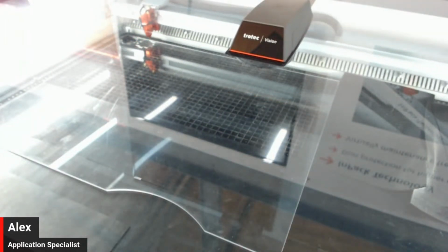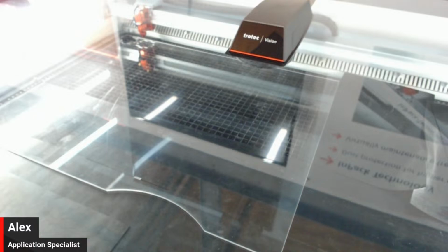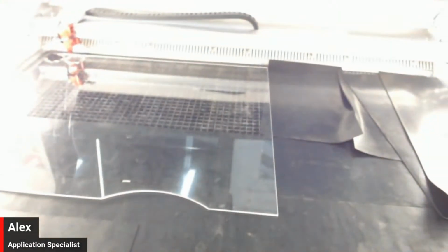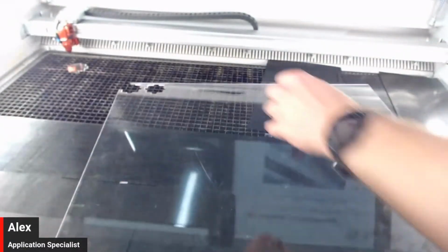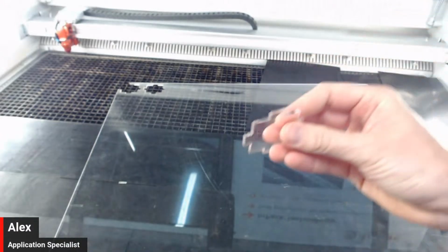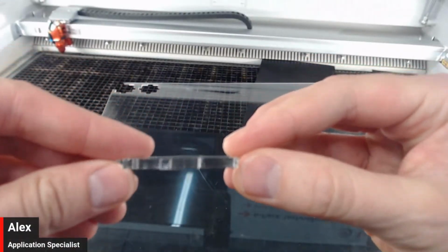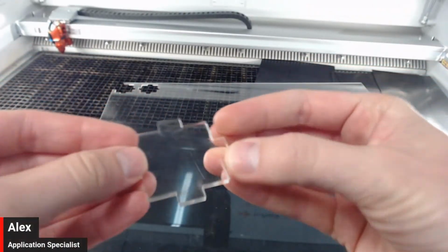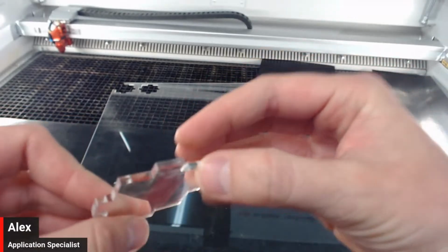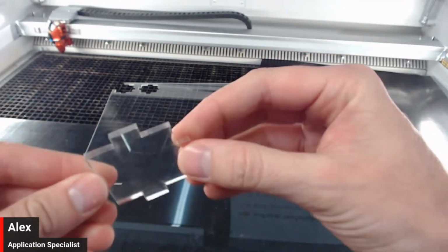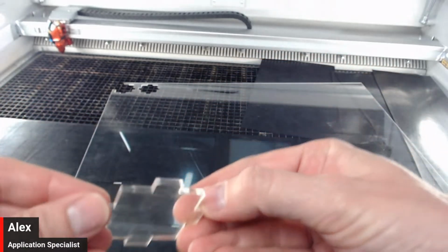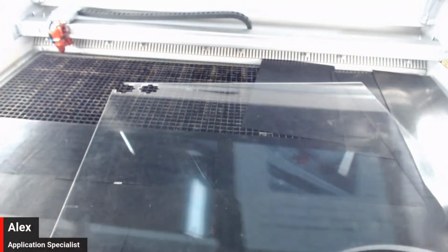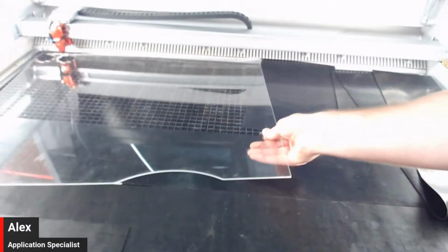So much faster cut, a lot less flashing on the actual cut itself as well. I did still see a tiny bit of flashing, but that's good because it lets me know that it has definitely cut all the way through. So we'll have a slightly less glossy edge, but I'm not getting any big marks on there. And of course, any risk of flaming is greatly reduced by using that correct combination of power and speed. So a nice, quick and easy way to make an adjustment.